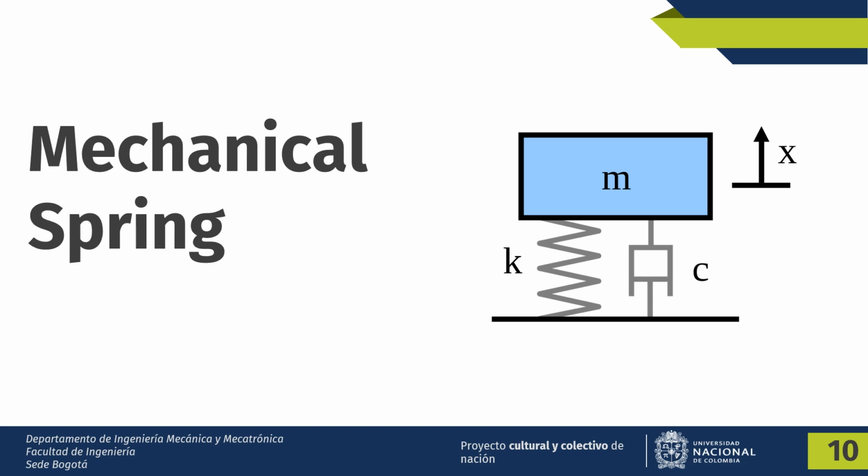Resistive accelerometers use a strain gauge, measuring the change of resistance and converting it to an electric signal with a Wheatstone bridge. These sensors are used in applications when high precision is needed.